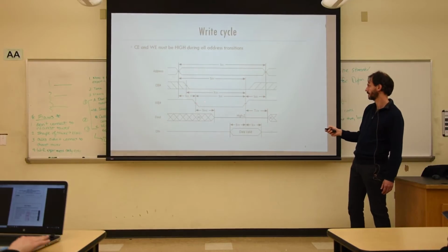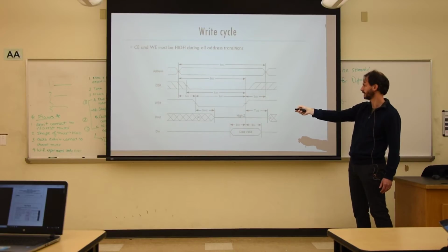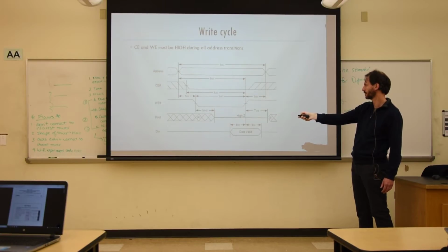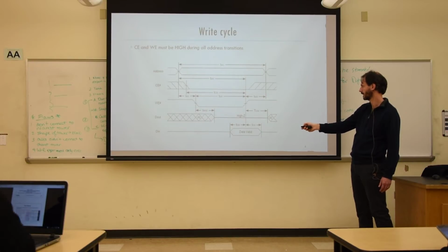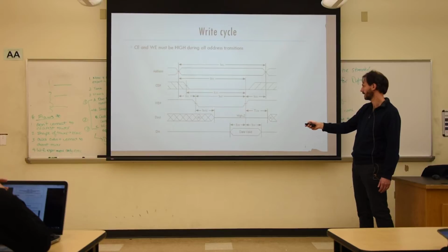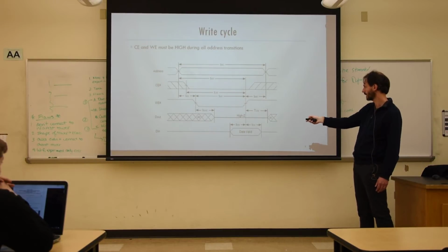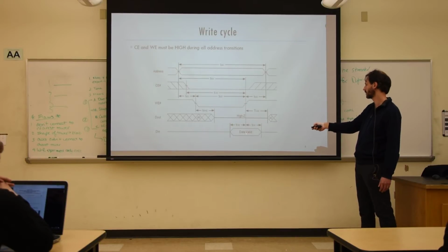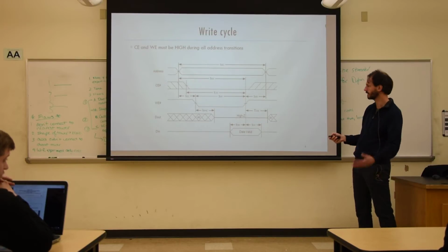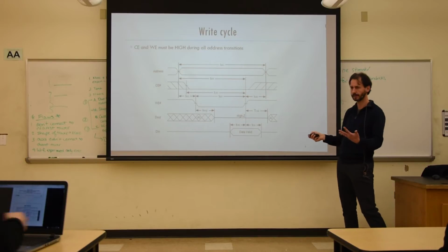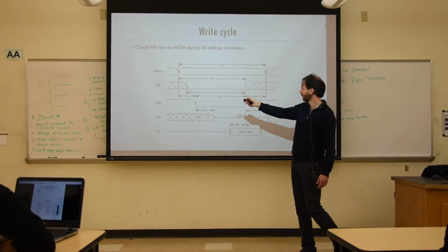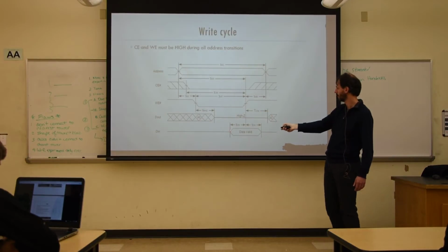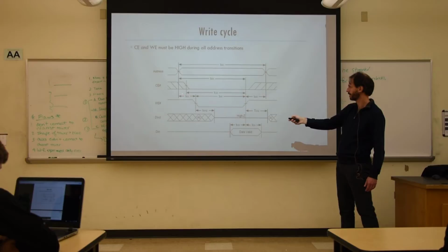It's kind of hard for me to see now, but you will indicate with that CE signal, I think. And then at some point you want to, for example, write something, and in the meantime you want to make sure that the data is actually in there and is valid. So that's over here. Once the data is valid, you go up here, and then you can actually write the data. So you have to look at this sequence. Right now I'm also studying this data sheet myself, but you want to go through these steps yourself.